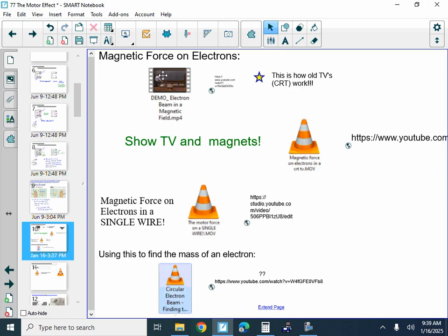And so in this one, there's going to be an electron beam. And it's really how old school TVs work. You have electrons flowing from a thermionic emitter, they call it, but basically they heat up and put a voltage on a type of metal in the back that boils off electrons, how they refer to it. Those electrons then are accelerated towards the screen. They travel from the back to the front, and then they get directed side to side and land in a certain spot to paint the picture, basically draw the picture that you see dot by dot. Pretty amazing technology, actually, that they're able to direct electrons and get them to land exactly where they need to be to make a picture. This is how old school TVs work.